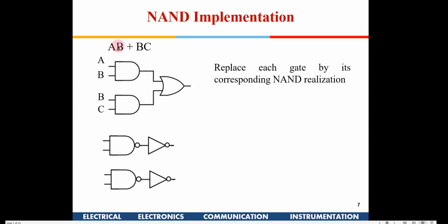Okay, this is the function which we got from the K-map. Now we have first made the NAND OR implementation. Now we have just replaced these two gates with a NAND followed by an inverter, right? So this becomes AND. So this is what we have done.